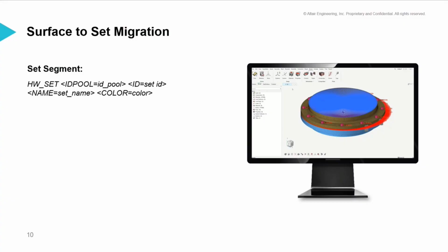Moving on to the next interface, which is the PERMAS interface. We did some migrations. One is it was all contact surfaces earlier. This is part of unification across interfaces, and it becomes very easy even from solver conversion to map these entities across interfaces as well. As Yuvraj also mentioned, the CONVG card, the thermal migration, is migrated to a load entity. So even in Abaqus, the star film is in the load entity.